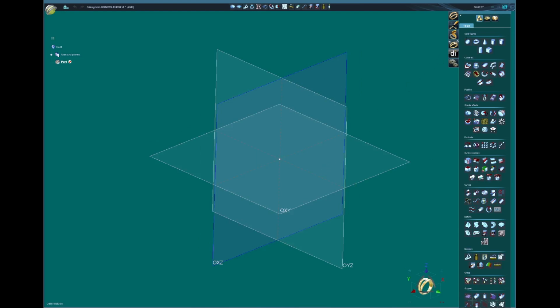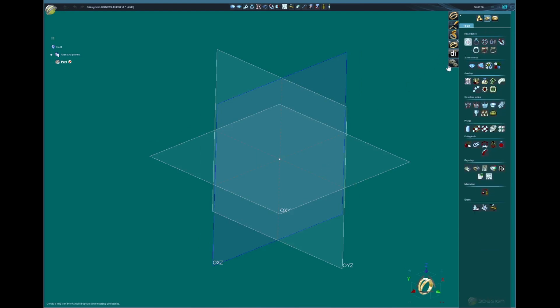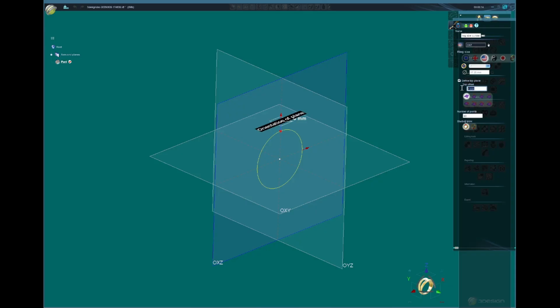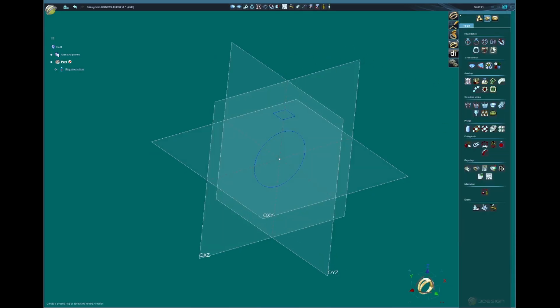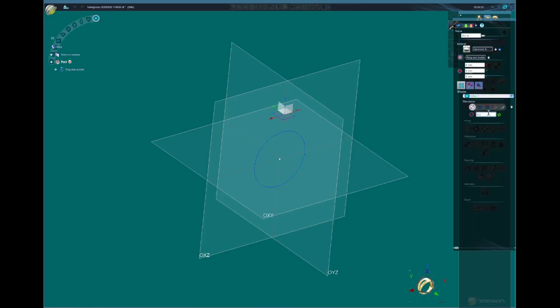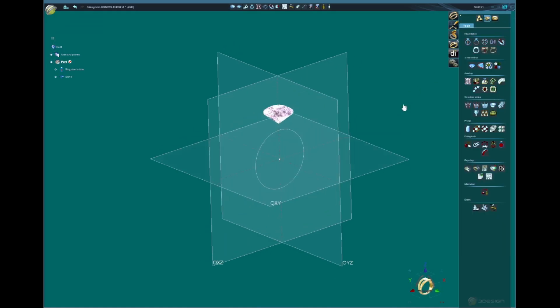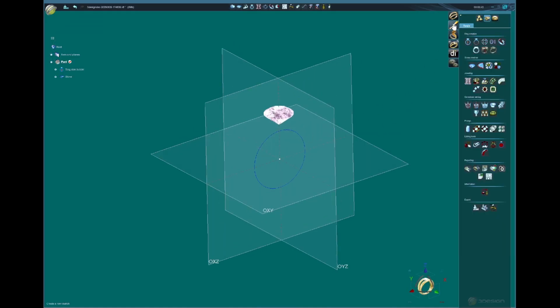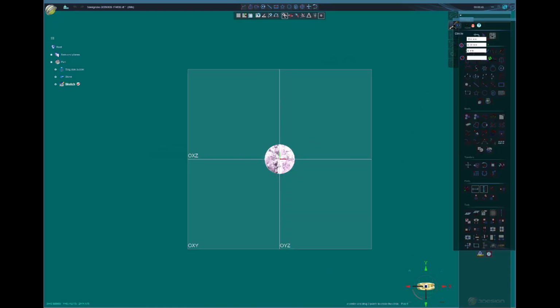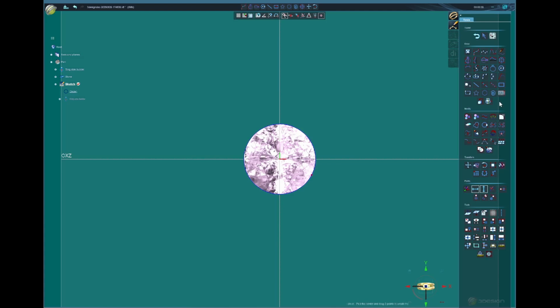Let's start. We're gonna go with size 7, and for the top plane we're gonna do 5.5 millimeters. On this plane we're gonna go with a stone of 8.2 millimeters, and I want a tourmaline. All right, so in the same plane we're gonna get two round shapes, 8.2 millimeters for our bezel, and I am going to